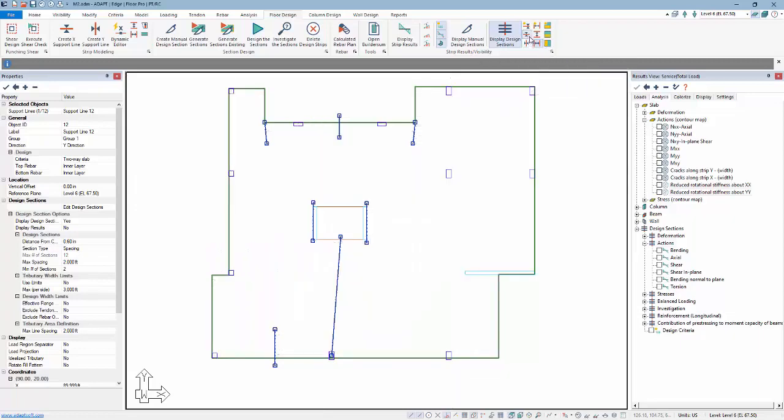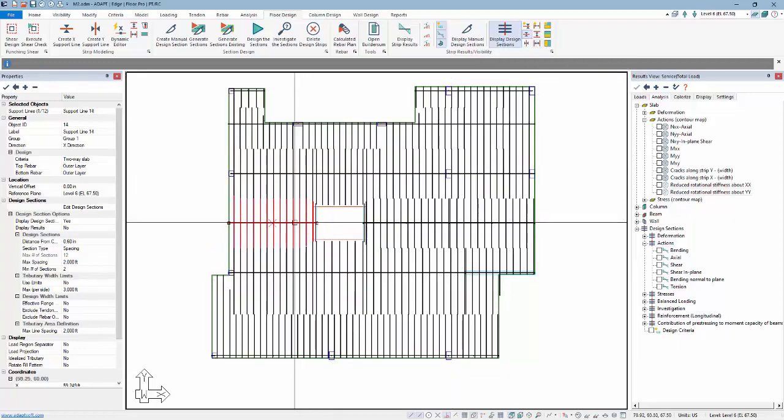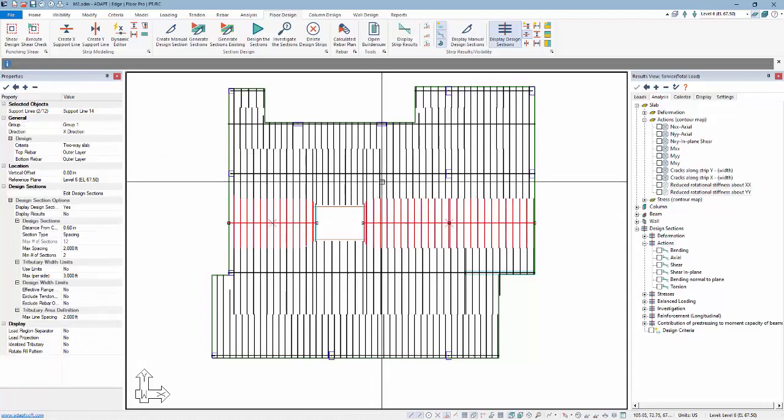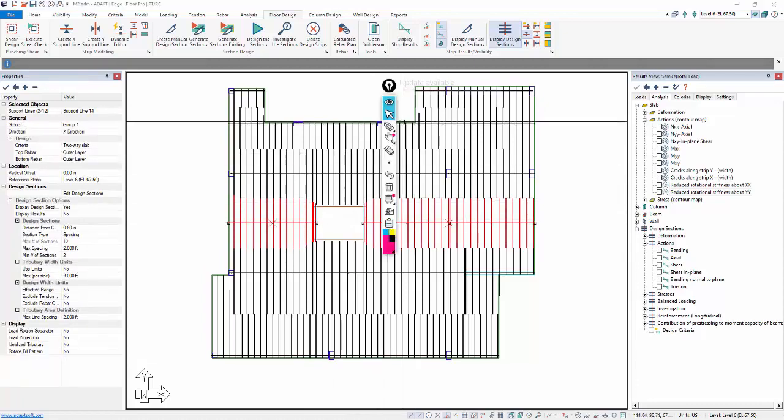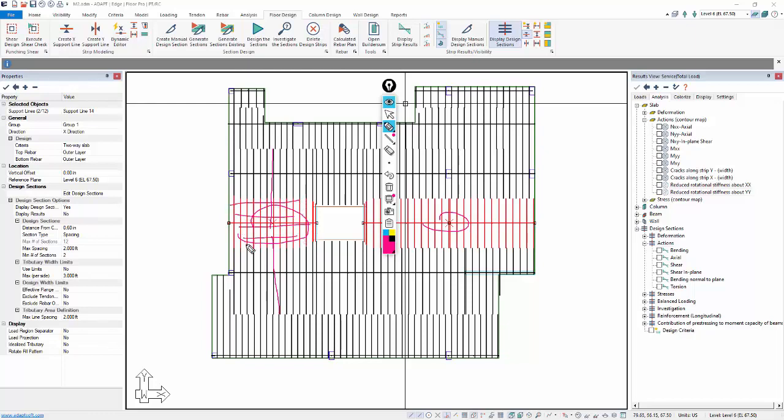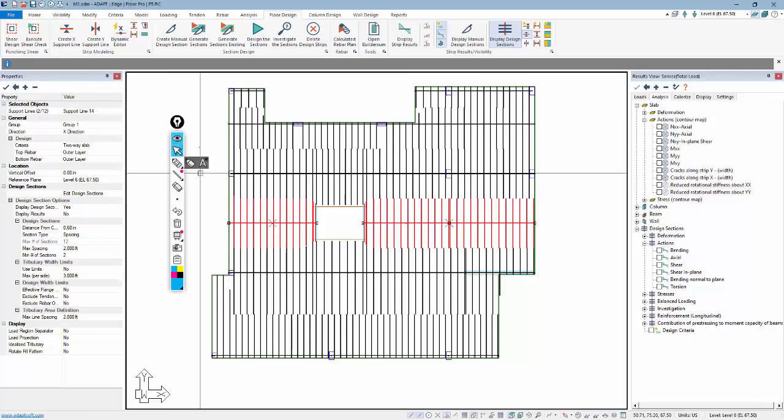In the other direction, in the X direction, we added a couple of strips here and over here just to refine the design cuts. Earlier the cuts were being integrated really from here all the way down to here and then like so. So we just brought in this cut and this cut just to break that up slightly. This is a uniform direction, so we still have uniform cables through this region here. We have banded cables. Let me color that in blue on the outside. So these bands pick up the uniform cables in the X direction for those new strips that were added.